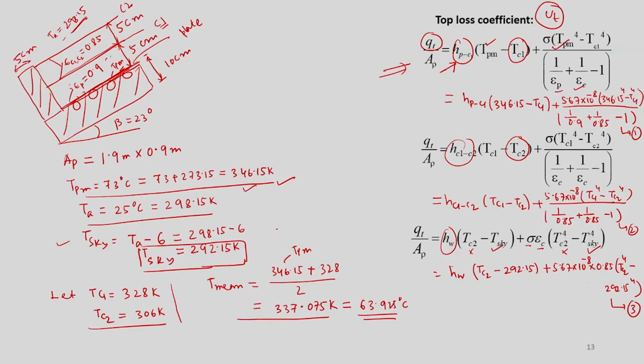So, if we calculate it, it is found that nu, that is kinematic viscosity, is 1.9348 into 10 to the power of minus 5 meter square per second, and K, thermal conductivity, is 0.02837 watt per meter Kelvin, and Prandtl number is 0.7192.